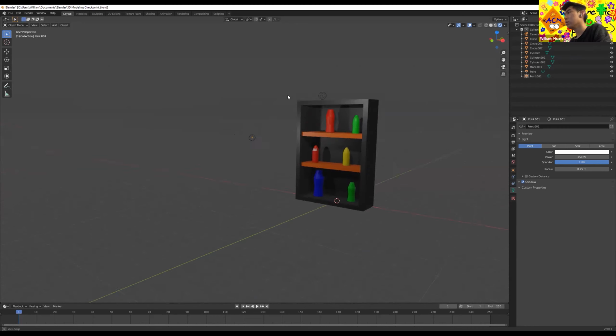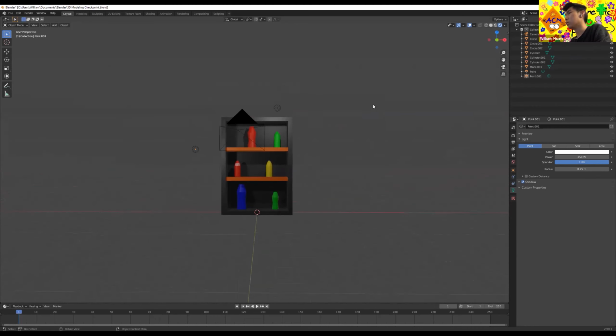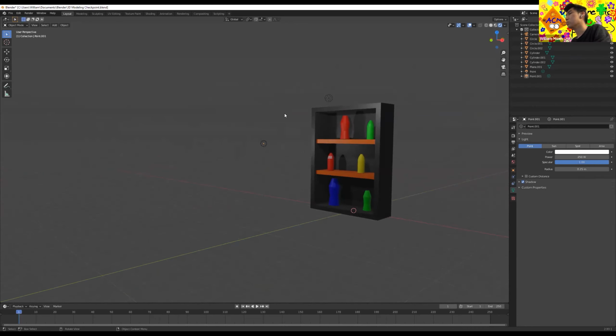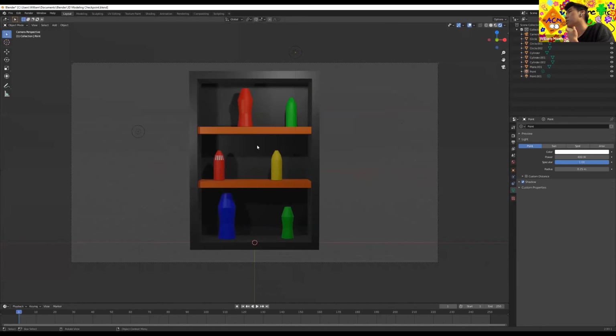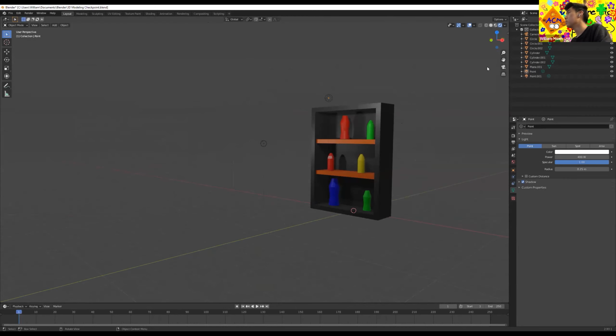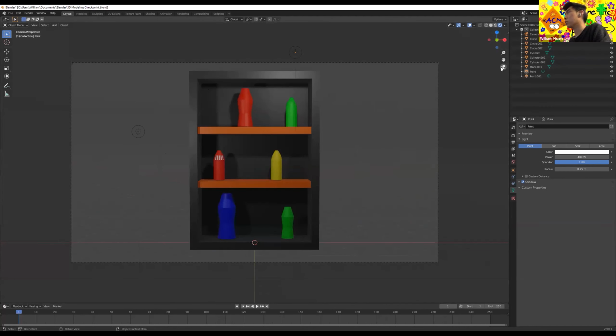Okay, finally, if you are satisfied with your image, first of all, save the project. And then, how to see camera view. That's important. Click on the right bar, there's a camera icon. If you click it, it'll go to this view. If you click it again, it'll exit the view. What you see in the camera is what you're going to be rendering.